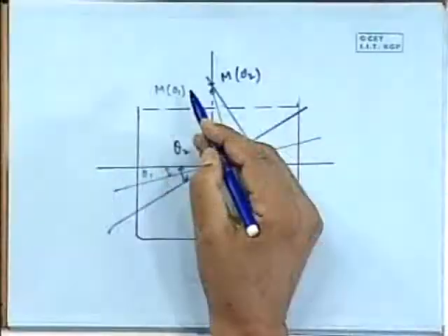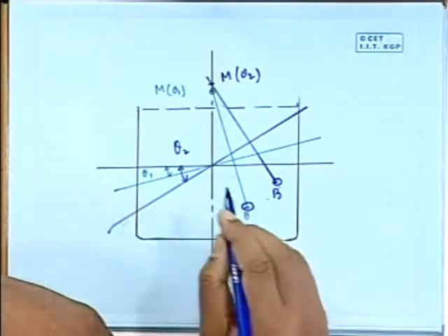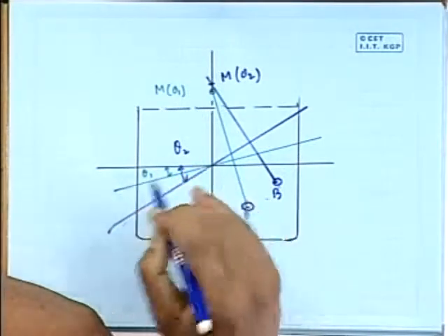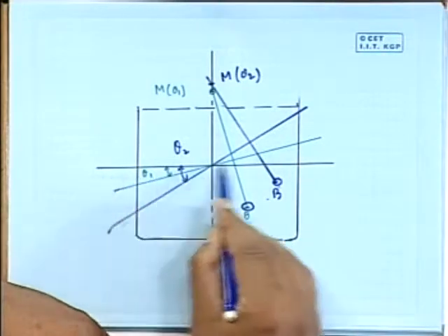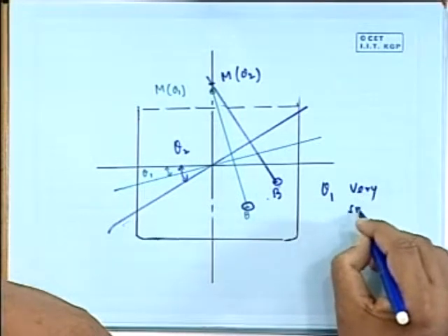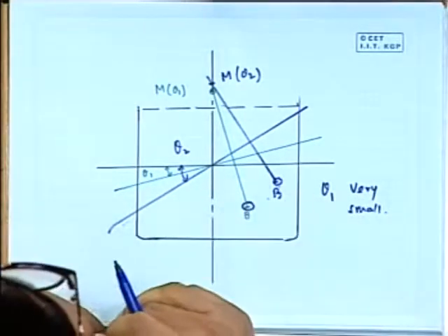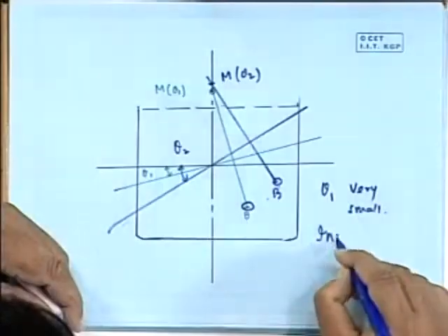So we must be very clear what we mean by the word metacenter. This inclination point, we are seeing this. What then happens is that in initial stability, we would like to know if I tilted it by a very small angle, see if I make theta 1 to be very small, should the vessel stay in that position or not? Our purpose of studying initial stability